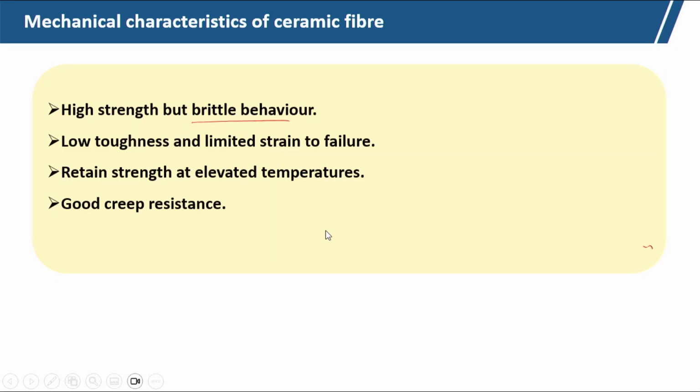So, for those applications we can use this ceramic fiber. It is sensitive to surface flaw and micro crack. So, during production, if there are any micro cracks or surface defects, then the mechanical characteristics will drop drastically.